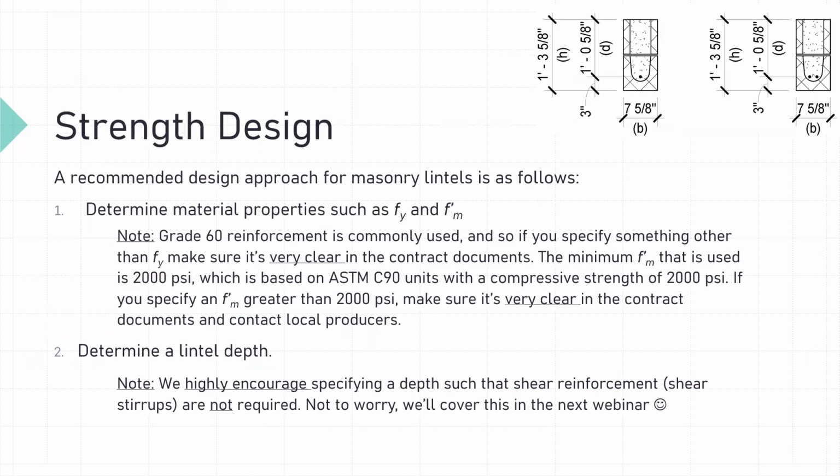In terms of designing lintels, we have an approach that they go through in Strength Design of Masonry, which is what I typically use for designing lintels. First we determine our material properties. Typically we're going to use grade 60 reinforcement.